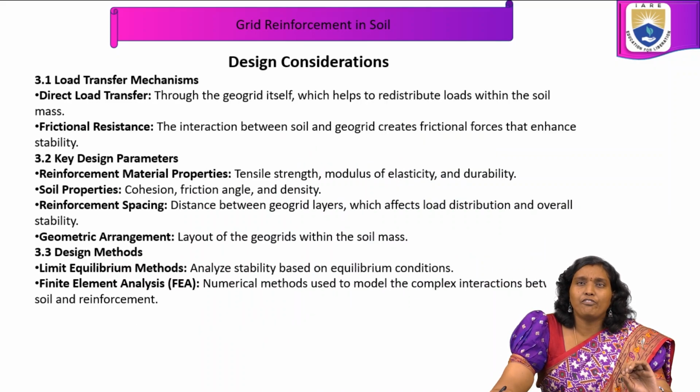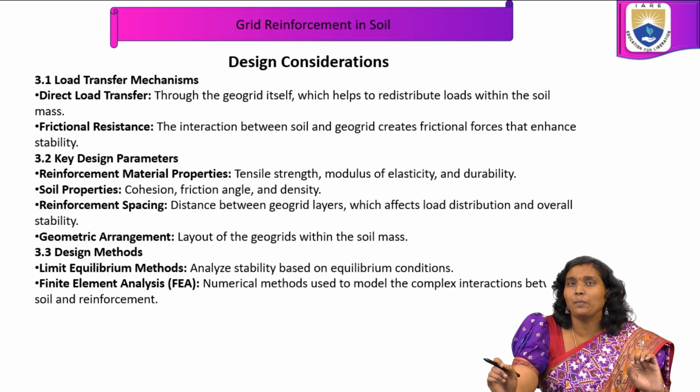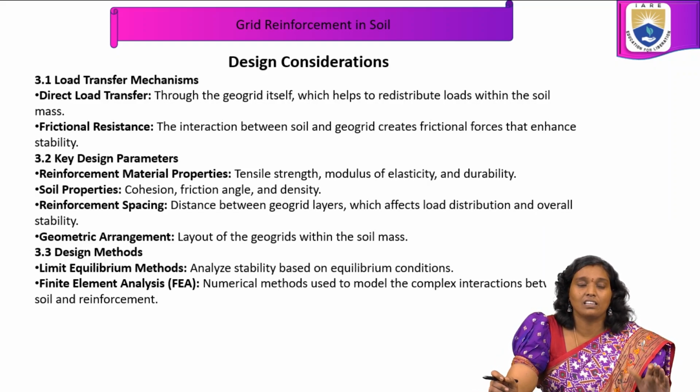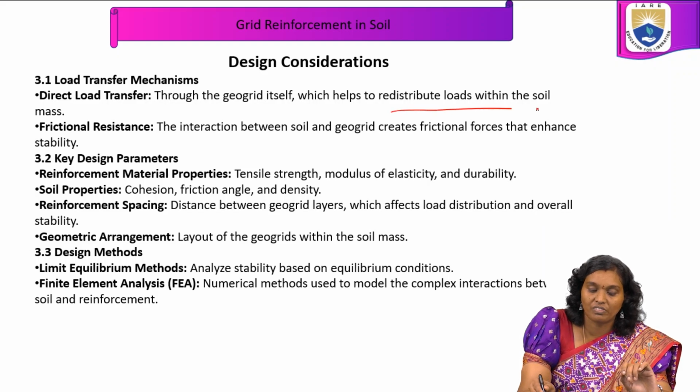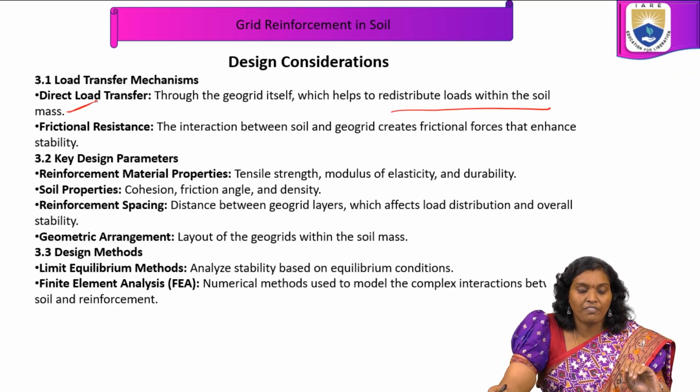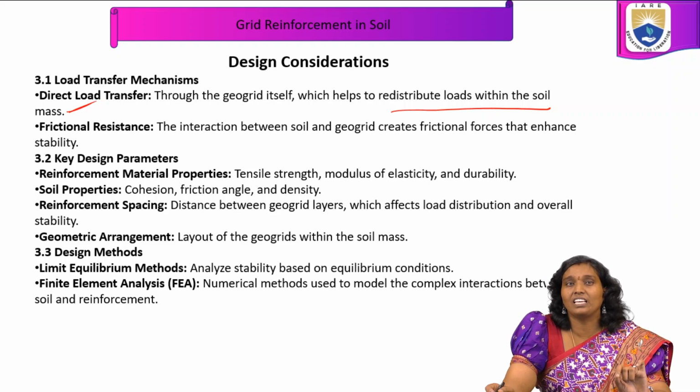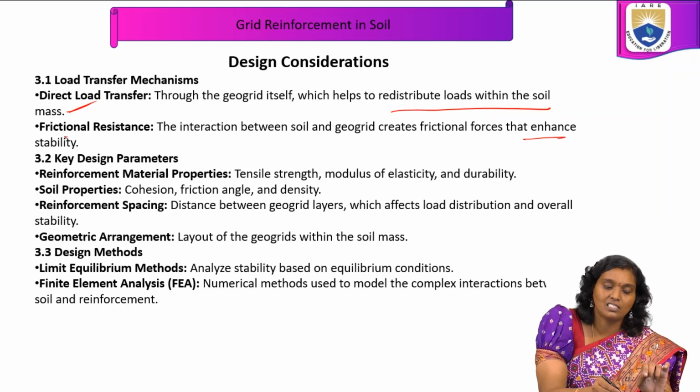In grid reinforcement in soil, various design considerations are involved before designing the grid reinforcement. We have to consider the load transfer mechanism, that is direct load transfer, and also the frictional resistance. Through the geogrid itself, it helps to redistribute the loads within the soil mass. In frictional resistance, the interaction between the soil and geogrid creates frictional forces that enhance the stability.